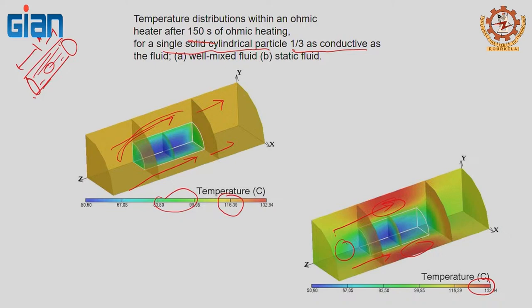So the point here is, in the ohmic heater, if you have a change in electrical conductivity between the liquid and solid, you could have different heating happen in the liquid and solid, and then you're going to have non-uniform temperature distribution. When you have non-uniform temperature distribution, that means that you are not going to heat the entire mass the same way we originally thought possible. That means you are going to potentially have surviving microbes there. It's probably going to be a potential food safety problem.